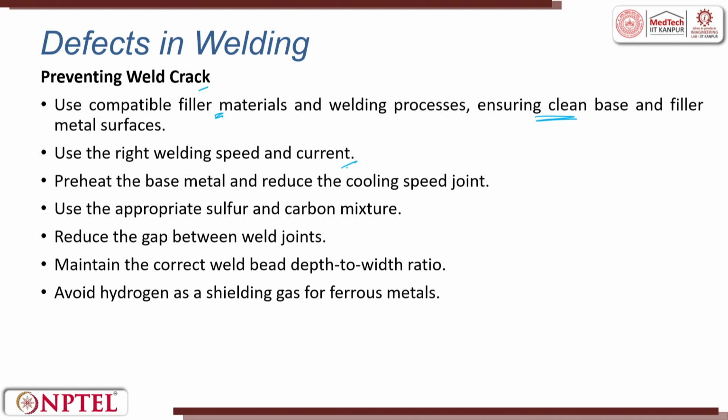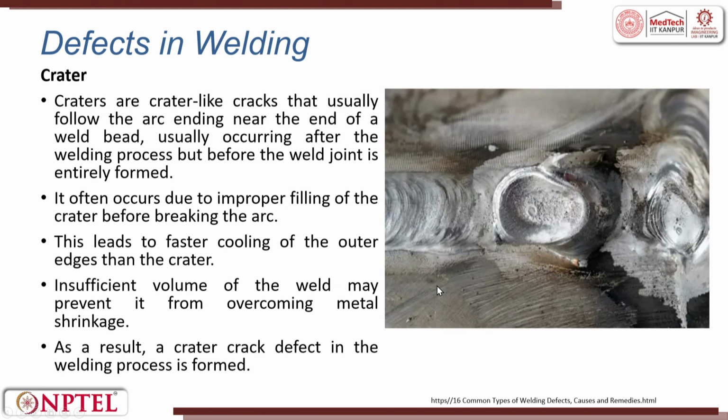Then use the right welding speed and current. Then preheat the base, because you are playing with the wettability and cooling speed. The sulfur content in the base has to be reduced. The gaps used in welding and the arc length have to be maintained. The depth to width ratio is important. Avoid hydrogen as a shielding gas for stainless steels.